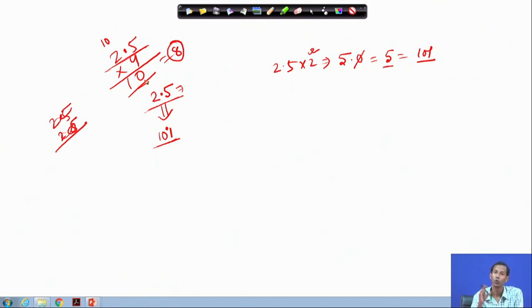If I do not want this error, which accumulates from truncation of the fractional part, I need to hold the original value. So for 2.5 I need the value 101, multiplied with 4, and I need the result to be 10.